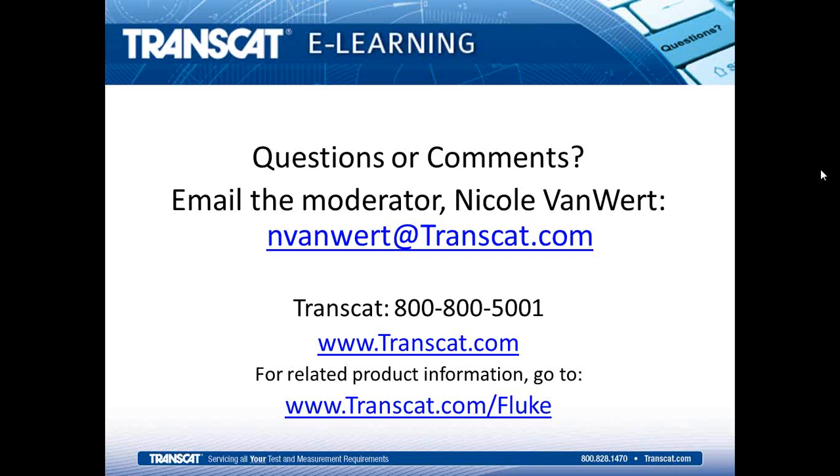The challenges with oil baths are that the trade-offs are that they don't move temperature very quickly at all. They're typically fairly slow to change temperature, and the range is fairly limited with fluids. We can cover minus 200 up to about 550 C with fluids, but it takes different types of fluids to do that. In a dry block calibrator, it's pretty easy for us to move quickly and cover a broader range of temperatures. So there's pluses and minuses to both situations, but typically speaking, baths would perform better in terms of keeping those uncertainties as low as possible.